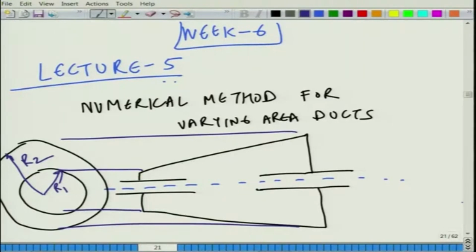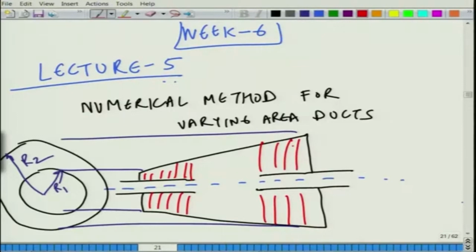The problem really here is that to analyze the wave propagation using Webster's horn equation, when you try to solve this for sections like this, unfortunately there is no analytical solution for such a system. Analytical solution does not exist. Basically, for areas in which wave propagation is in the annular region, where the annular region comprises a space that is bounded by a uniform duct and a gradually varying conical flare.